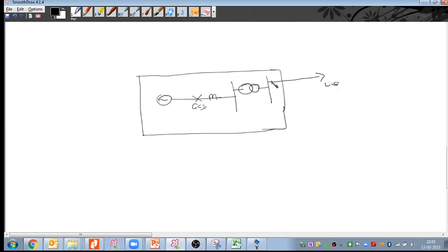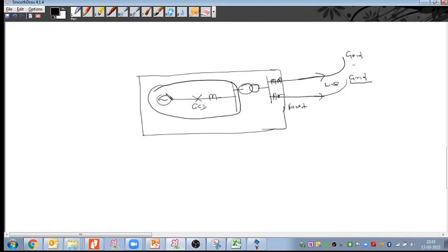So if we are working on these locations, we can directly take the fault level as per the voltage, because there will be back feeding also, and that will come from the grid, right, Sivam? Yes, that will come, because when we do the synchronization we take the reverse supply from the grid, so we can take the fault level as per the grid, as per the voltage. And when it comes to these locations, you are telling that we can calculate the fault current based on the percentage impedance.